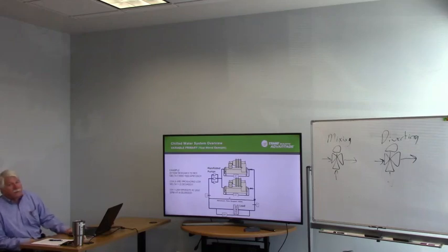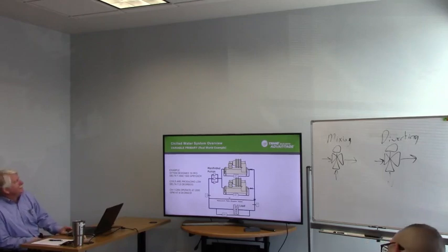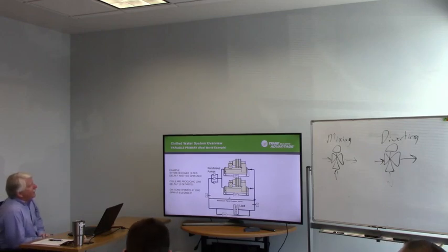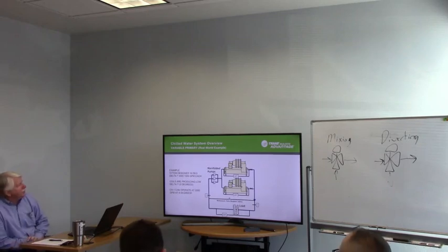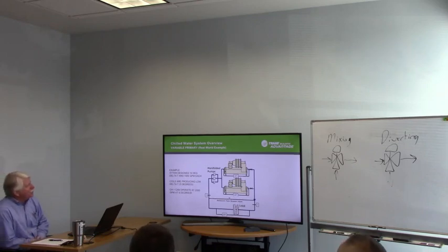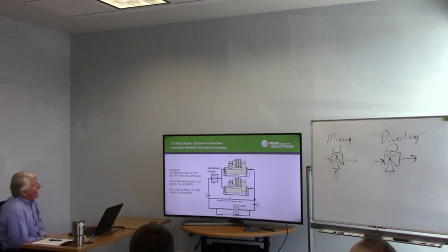Now, we get to use our math brains again. The system is designed at a 16-degree delta T and 1,000 GPM on each machine. Now, the coils, for some reason, are producing a low delta T. Can I operate at 2,000 GPM and an 8-degree delta T?